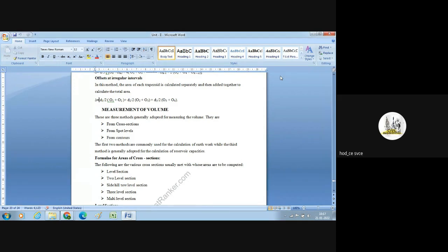As you know how to calculate the area for different geometrical shapes, if you have irregular boundaries, in that case try to implement the possible geometrical shapes. So if you know the coordinates of each and every point, based on the coordinates we calculate the distance of each and every side and form triangles if possible, and calculate the area based on the coordinates.